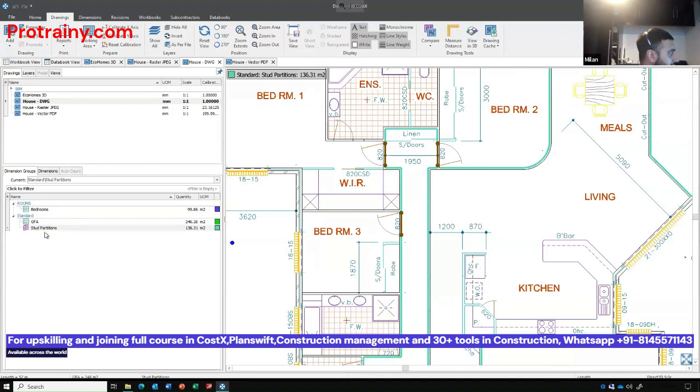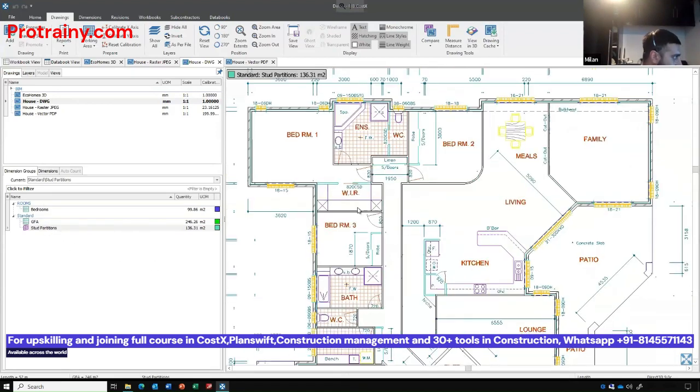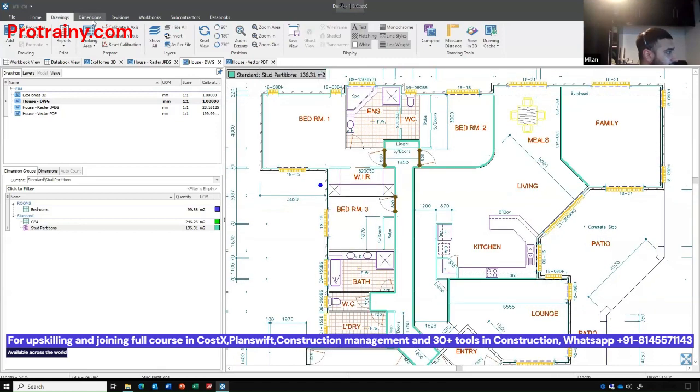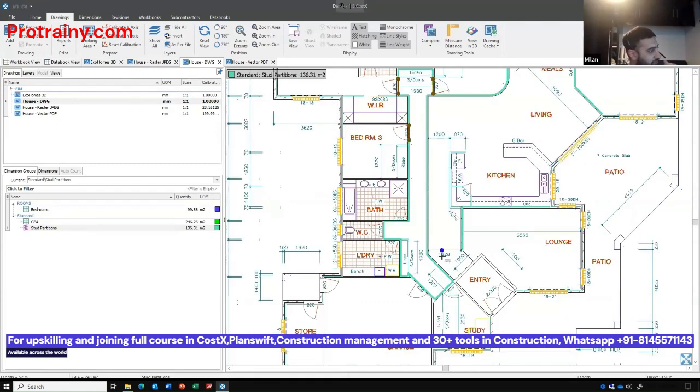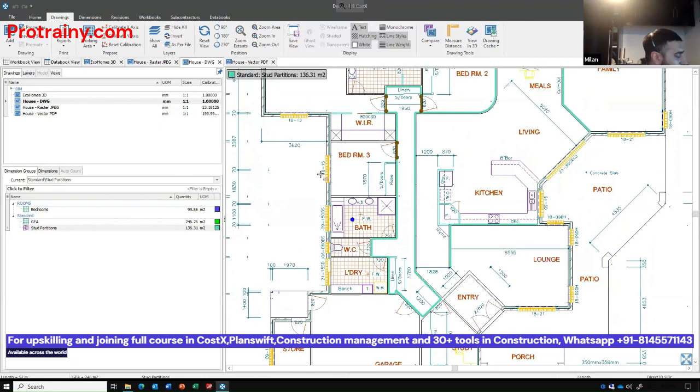So that's measuring length. So I've measured some areas, I've measured a length. This applies the same for structural drawings, M&E drawings, same thing. MEP, if you're measuring ductwork, you're measuring pipes, same thing. Reinforcement, spacing, there's special functions for doing spacing and reinforcement if that's what you need to do.